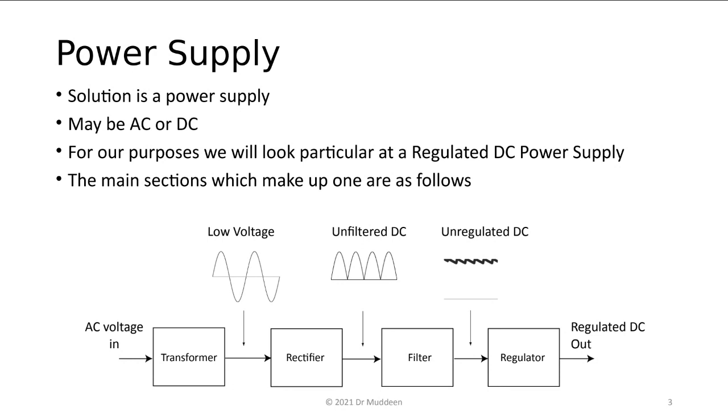Those of you in the signals and systems class this morning will remember me talking about modeling and blocks. So in terms of the block layout for a regulated DC supply, first off, you have a transformer at the front end. The transformer is going to take the line voltage coming in, maybe 120 volts here. In other parts of the Caribbean, it may be up to 220 to 240 volts, depending on where you are. It's going to convert that to a low voltage, 12, 15, 18, 24 volts AC. At that point, you have to convert that AC into DC, and that's where the rectification comes in.